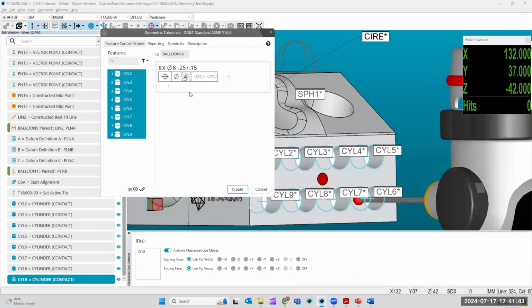And then to get the maximum material, you just hit the MC, and you can pick your modifying condition, M. And we pick the plus. Well, the first thing that comes up here is A, because it doesn't recognize what you're trying to do. Most of it does, but this one you have to pick from the drop down. It's C, make it match your drawing, B, and then A.